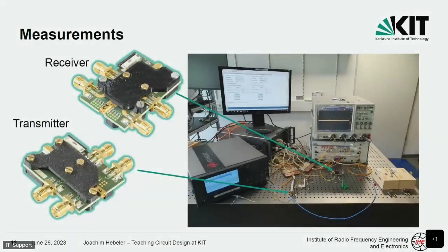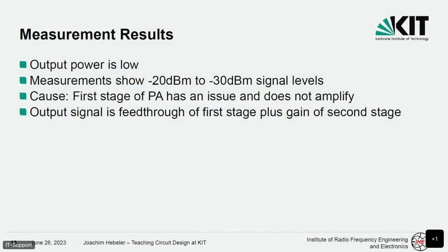The other problem is, it's here, or here. The PA has no output power. We measure like minus 20 dBm. Again, LVS is clean. The schematic was fine, but somehow this first stage is broken.